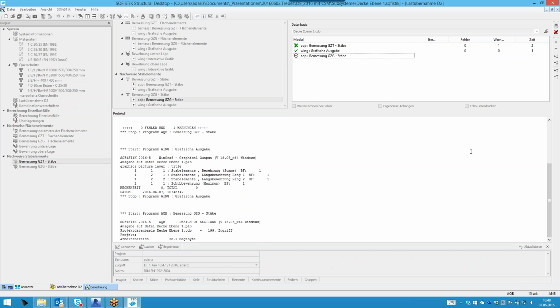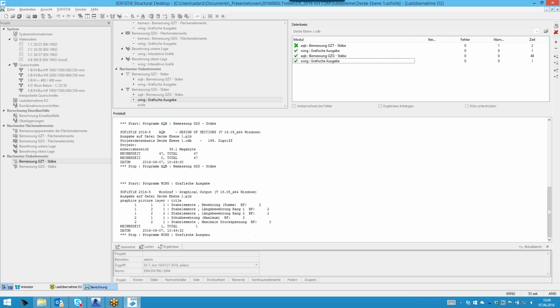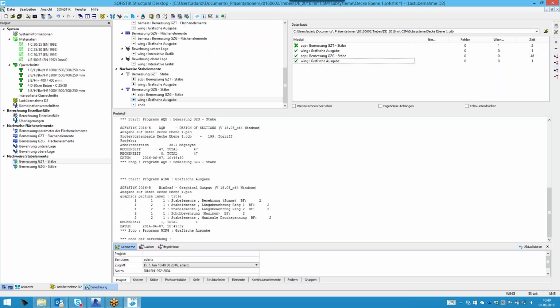Again, I will ask if you have any questions on that part. What we have seen now is using the Revit model for analysis and design in different methods. One method is generally the 3D system export for dynamic analysis and maybe wind analysis. The other concept is the so-called subsystem concept, where we can export only parts of the building and automatically generate the support elements of this part. Are there any questions?